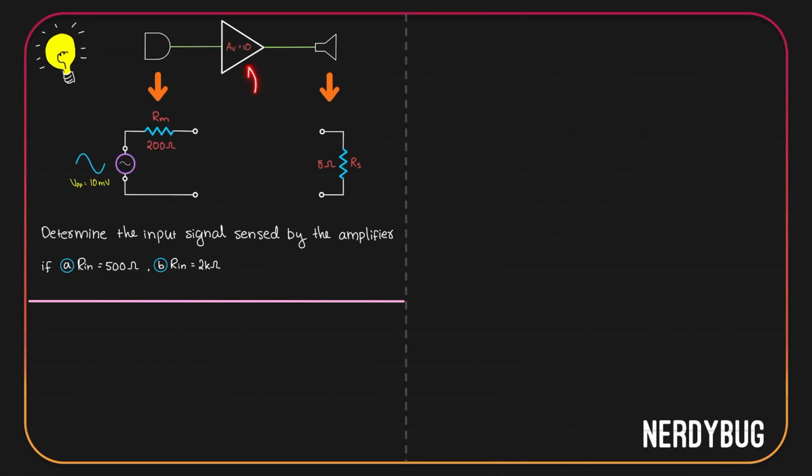We have an amplifier whose voltage gain is 10. Whatever is the input, output is going to be 10 times of that. Input is a mic, which basically gives a sinusoidal input. The mic also has its own resistance Rm. It is equal to 200 ohm. Output is a speaker, which we can model as a resistance Rs. It is equal to 8 ohm.